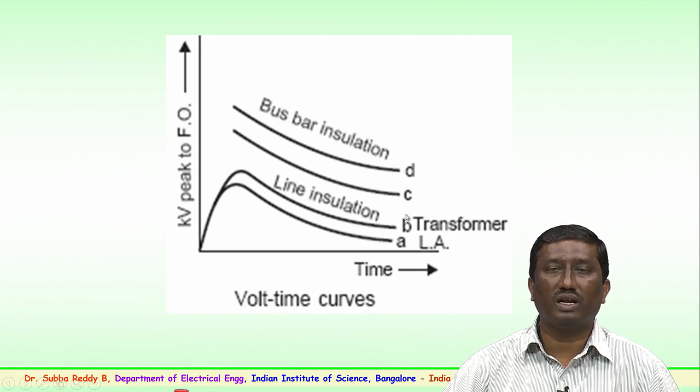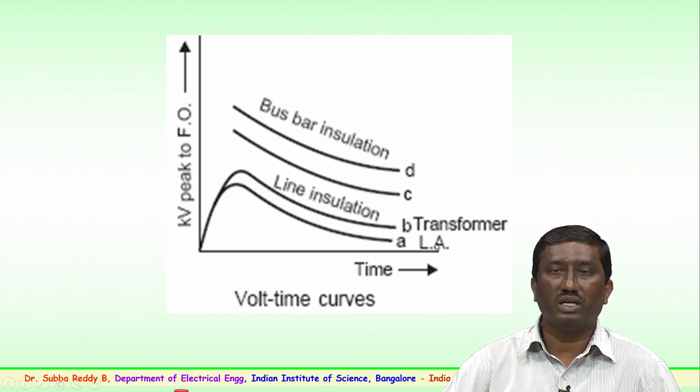To protect the transformer, we have a lightning arrestor, which has a lower insulation level than the transformer. So, in case of over voltages, failures, or abnormal conditions, the initial sacrificing element should be the lightning arrestor, which should conduct in the transmission system and protect the transformer. This is how the line insulation is designed. Further, beyond the transformer, there may be some other insulation which has been designed, like the bus bar and so forth.